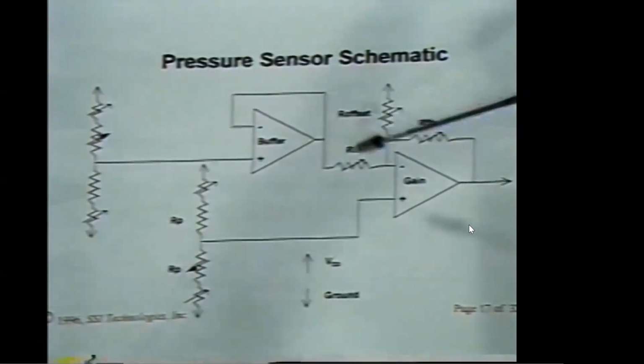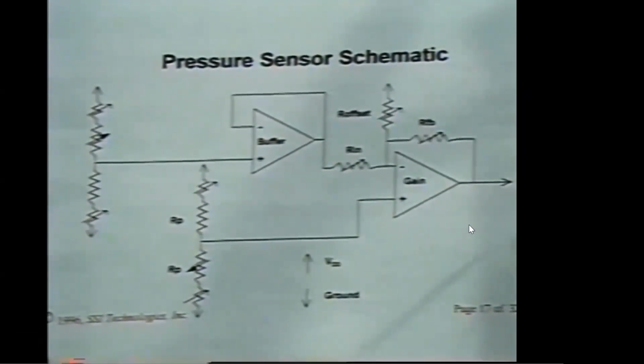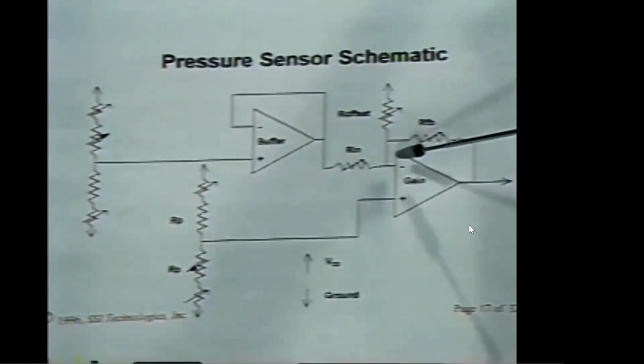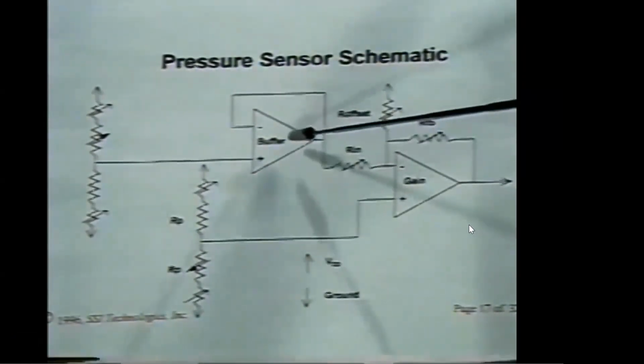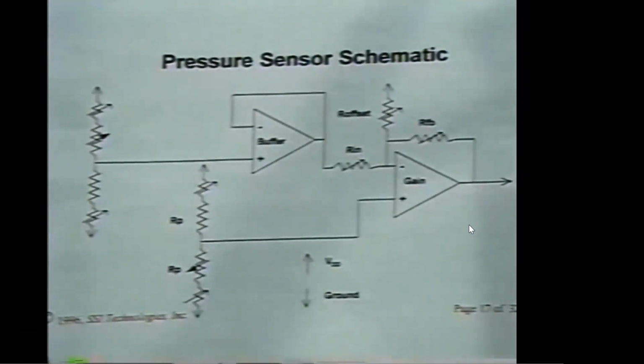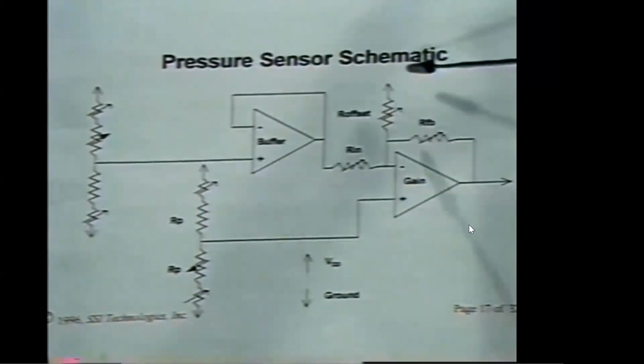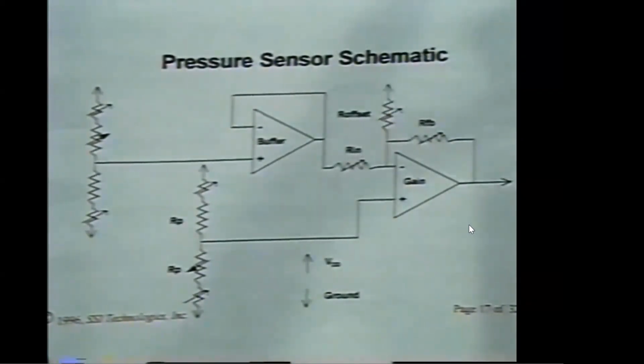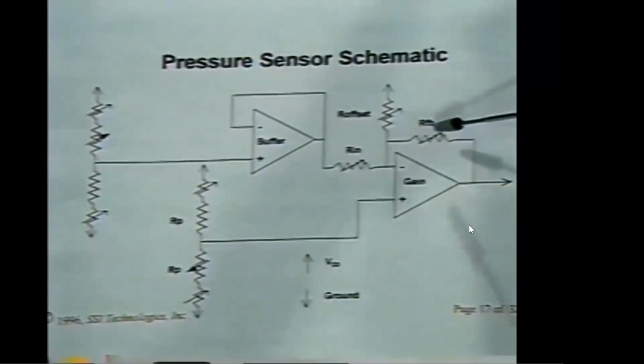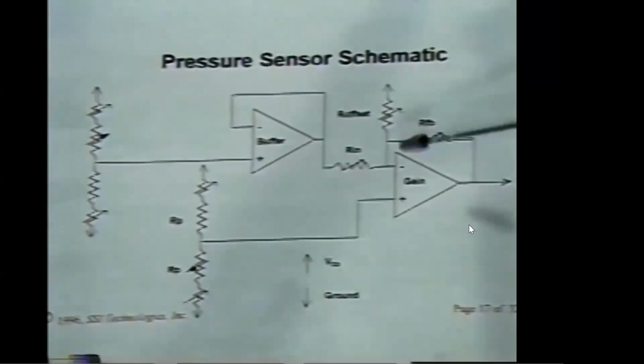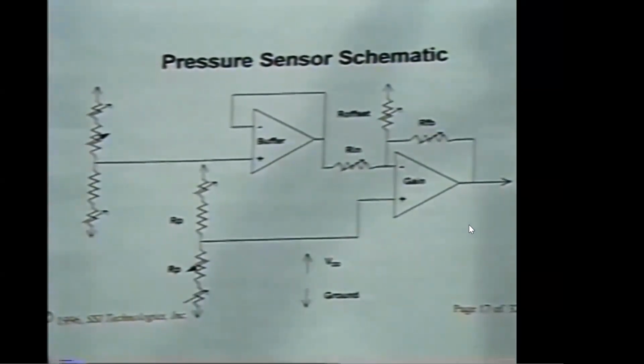And from that buffer amplifier, we run it through a gain to produce the output that is required by our customers. In the path between the buffer and the gain amps, we add additional resistor structures to do two things. One is to provide an offset for our die, according to whatever our customer desires. Second, we provide some, I'll call them dummy resistors. But these dummy resistors provide us with some temperature compensation, because then we can play some games with the doping levels of those resistors.